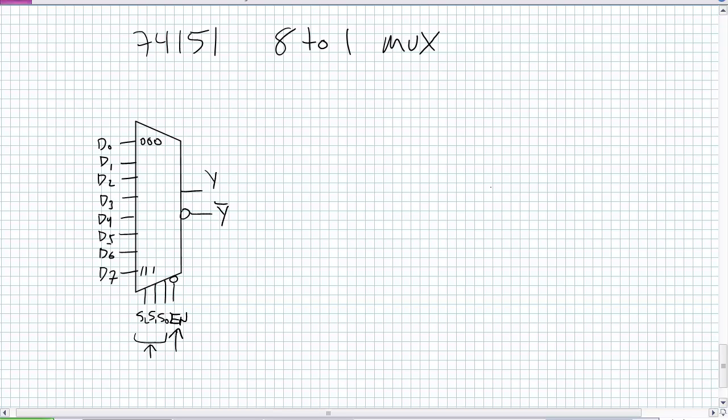One would think, let's say, for example, we're using the counter application. 000 goes to 001, 010, 011, so on and so forth, going from the possibilities of D0 all the way up to D7. And let's say everybody gets an equal share for a little bit of time and then it comes back, and you apportion it out to 1/8 of whatever that time cycle was. One would think that there's this clean and even transition from 000 to 001, and this super clean, snappy transition from 001 to 010.